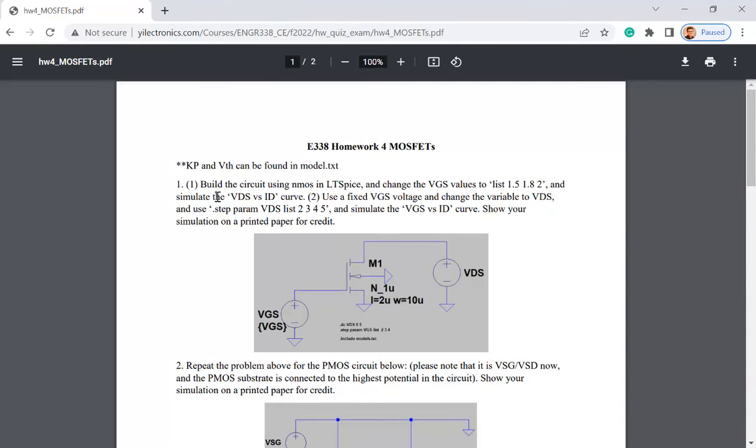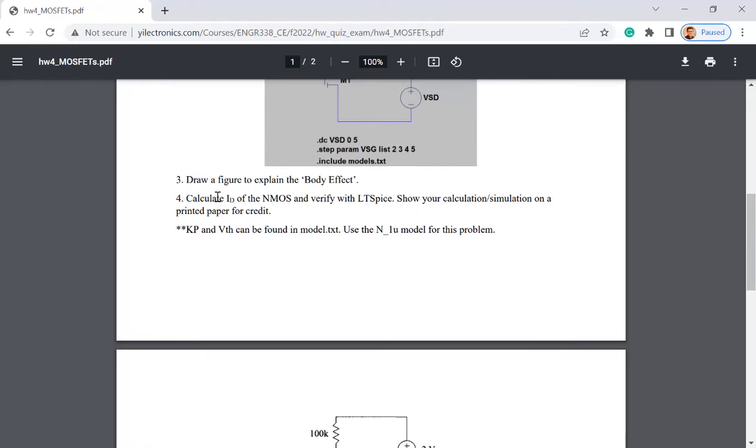So for using polysilicon wires as resistors, you can. Just don't put any silicide on it. I put the two questions in the same problem, which will confuse people. But if you know what you're doing, the polysilicon layer can be used as a resistor material. If you want to use it for different purposes, like just a conductor, you need to put silicide on it to reduce the resistance, but then it's not being used as a resistor anymore.